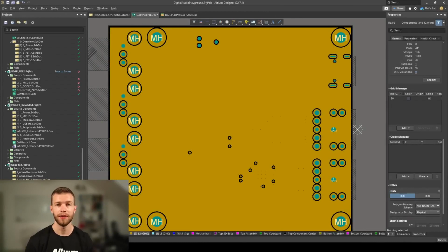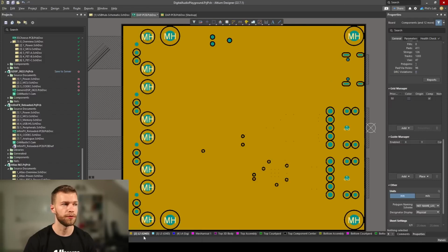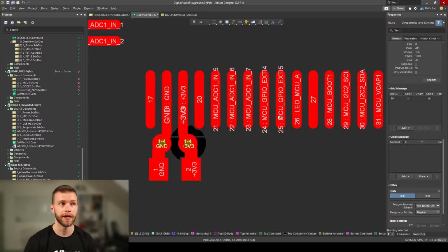The final tip I'd like to give you is using solid reference planes directly adjacent to any signal layer, as well as directly adjacent to any power planes you might have. Oftentimes in more complicated PCB designs and multi-layer stack-ups, you'll have more than one ground plane. Here are also some tips and some beginner mistakes I often see that you should avoid. In this example, I have a solid ground plane on layer 2 and on layer 3. On layer 1, I then might have signals.